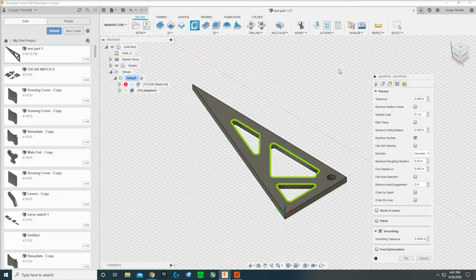However, there's more complicated things, for example, arcs, which is what we're using for the smoothing command. So an arc will actually, I believe, be like I1, J1, so it's I's and J's versus X's and Y's. And that, instead of using a bunch of dots that they're connecting, actually creates a nice smooth arc if you choose this smoothing command.